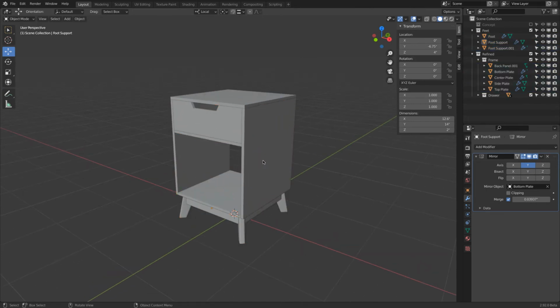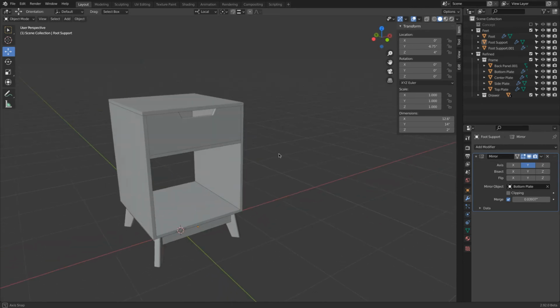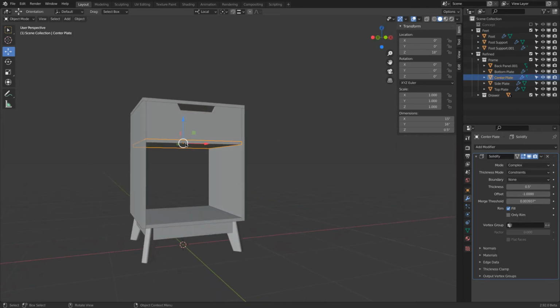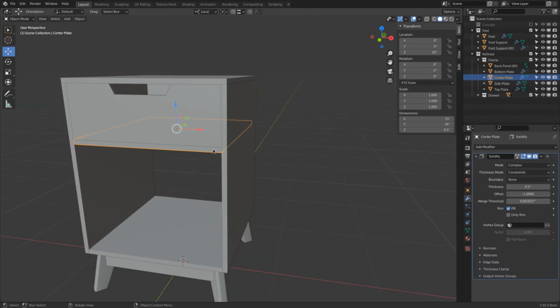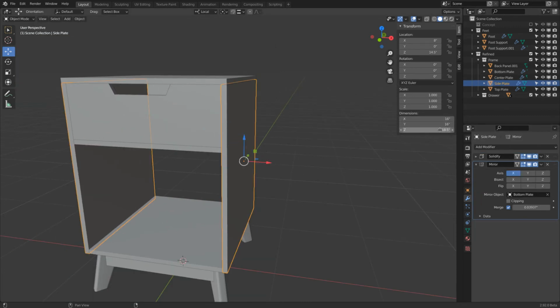Okay, so nearly done. Here comes the last tiny piece to fix to make this a tick even more realistic. This, it's difficult to connect. Here and there where screws and nails I could do something, but here, well, from the outside, I don't want to see connections here on the outside. So ideally I want this plate to go into this plate. Okay, so this has a thickness of 1/2 inch, so maybe 1/4 inch.